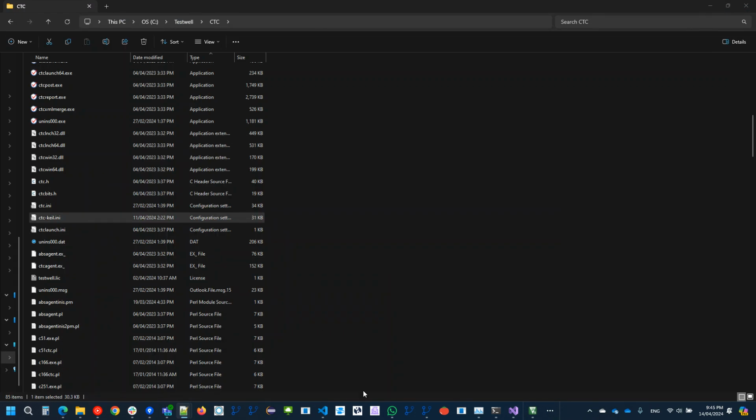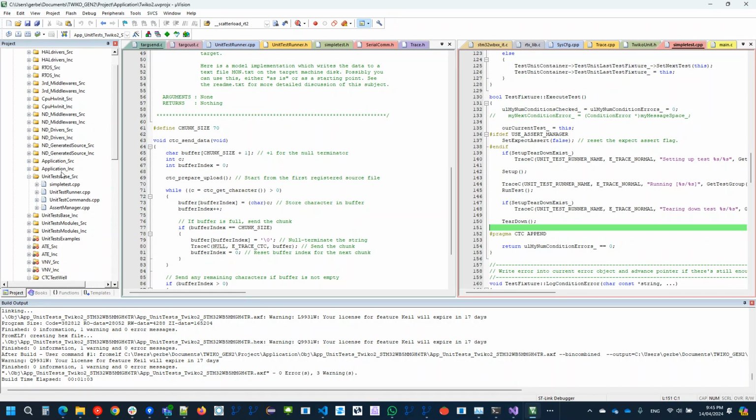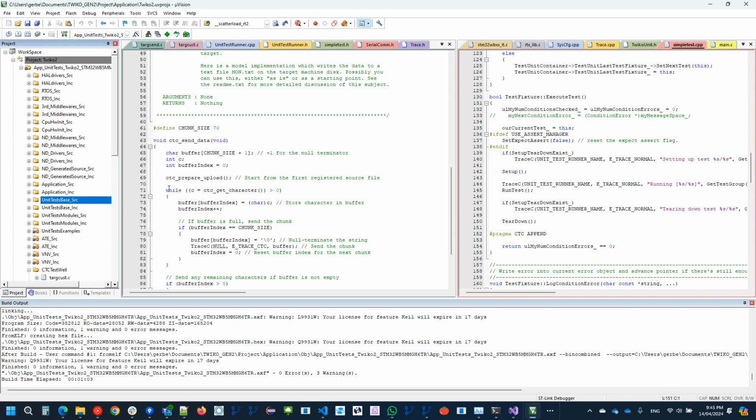Now, as you saw in our project, we have a lot of files. I don't want to instrument everything. I won't even have enough memory to instrument everything. I want to instrument only what really matters to me, which is the files that I use and develop myself, that I truly want to test at this moment. I have other files here that are from third parties and stuff like that. I don't want to test them. So I'm going to test only the source files of this folder.